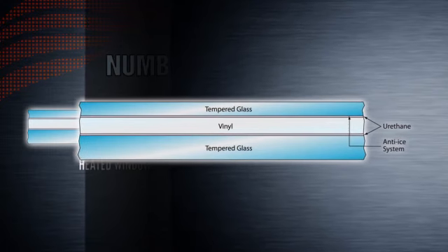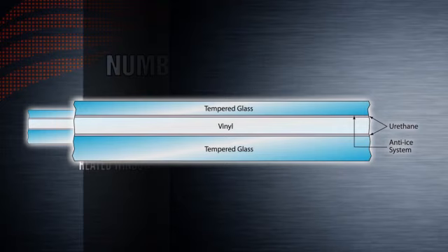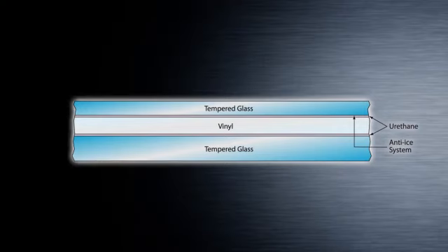Flight deck windows numbers 1, 2, 3, 4, and 5 consist of glass panes laminated to each side of a vinyl core. The inner glass pane is the thicker and carries most of the structural load. The vinyl core is a backup load-carrying member, and it prevents the shatter of broken glass if the inner pane breaks. The outer glass pane has no structural significance, but provides further rigidity and a hard, scratch-resistant surface.